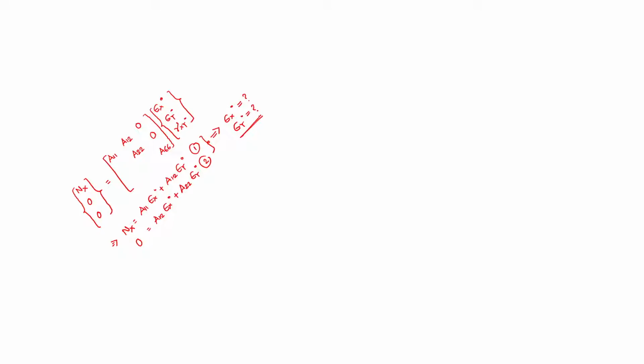Is that clear? This is not always true. Please don't take it for granted. But the kind of assignment examples I have given you, intentionally we have provided this, because 0/90 is symmetric, so A16 and A26 will not be there. Okay, and you have only NX. Even if instead of NX it could be NY, still it actually comes to only two equations, two unknowns, where NX is known, A11, A12, A12, A22 are known. Therefore, you can know what is epsilon x0 and what is epsilon y0.